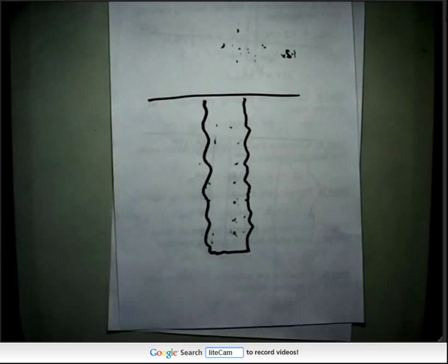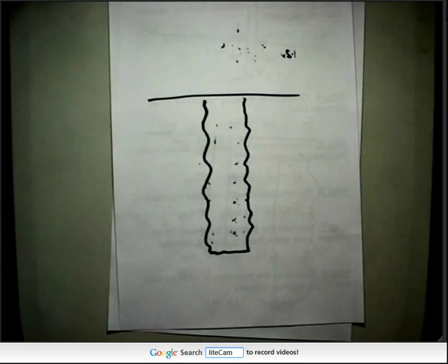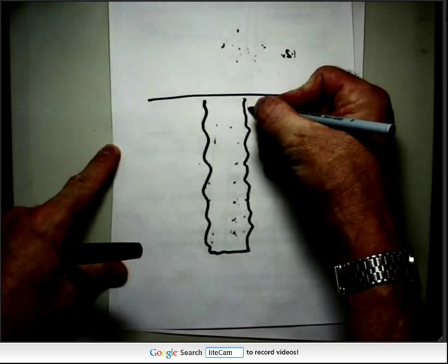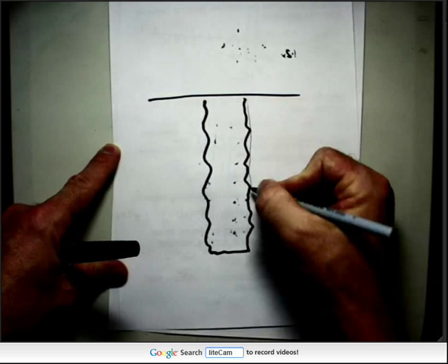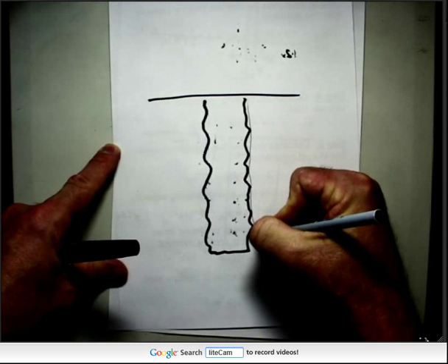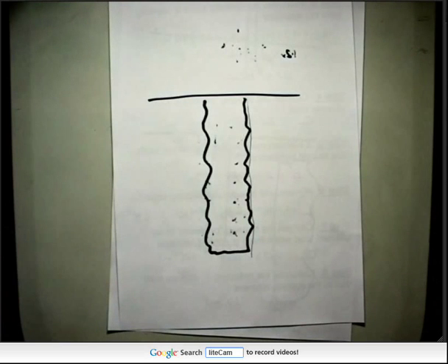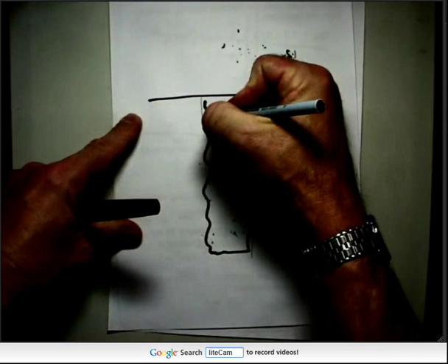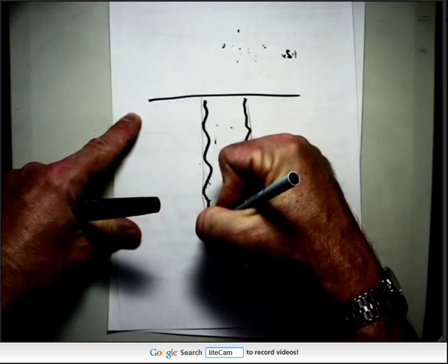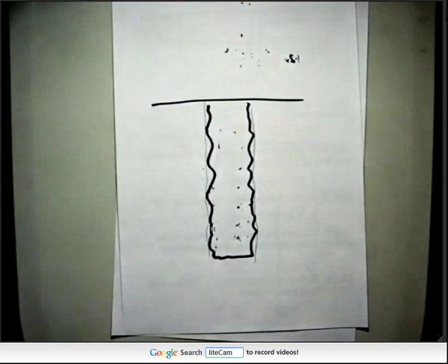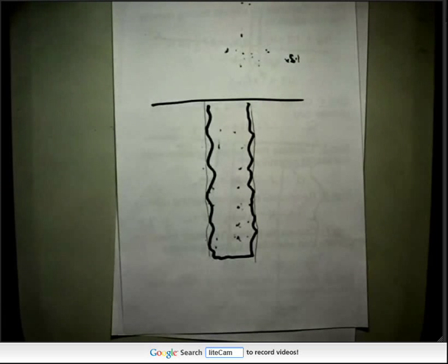and I've made it very stubby, the failure surface we get when we fail that pile, if we push it into the ground, tends to not follow the surface of the pile even. It tends to cut down like so. It will just shortcut between what we call the asperities, the lumps. So when the pile fails, the failure surface may not even be right on the surface of the pile, or at least it won't be continuously on the surface of the pile.